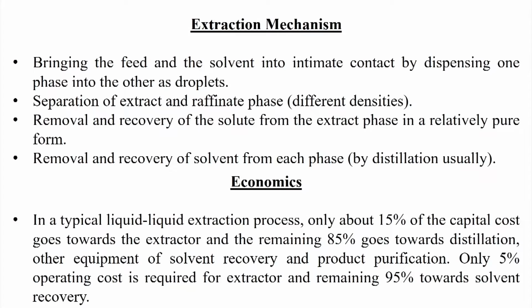Depending on the miscibility of the target component, that is the solute, in the extracting solvent, the solute will move from the carrier solvent to the extracting solvent. The second step is separation of the extract and raffinate phases, which depends on the density difference between the two solvents.